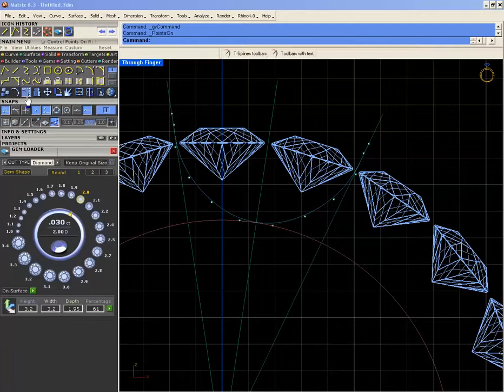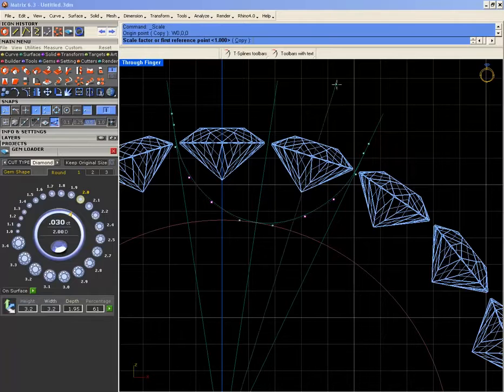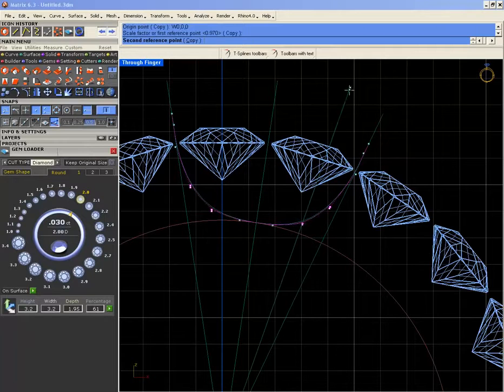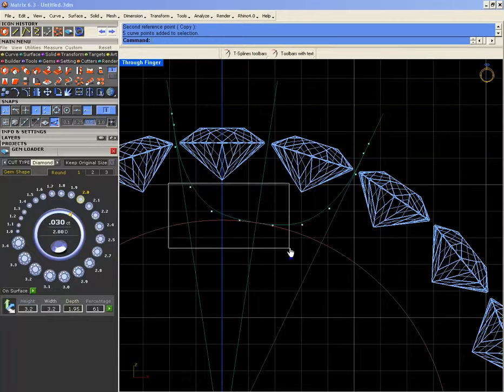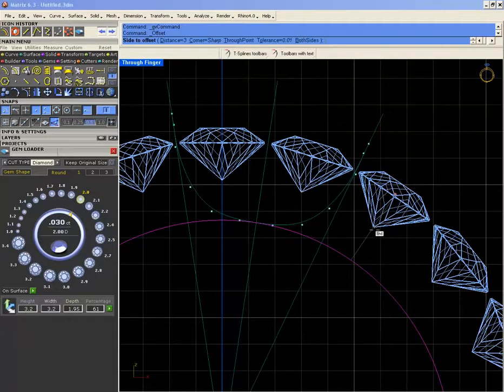Okay, and you can bring them down if you want. You can use the scale 3D, and that's it. Okay, the minimum thickness is gonna be 0.4, so the minimum thickness of the prong is gonna be 0.8, so I'm gonna offset 0.4 outside so I get this line on this one. So when I have a thickness, they touch. They don't overlap each other. Yeah, they don't come inside this ring, right?